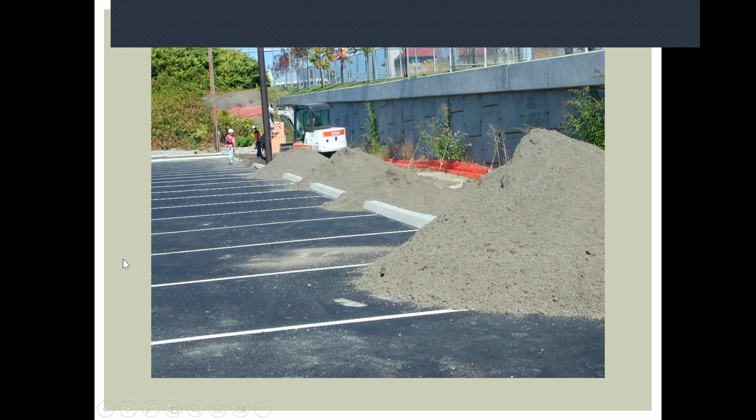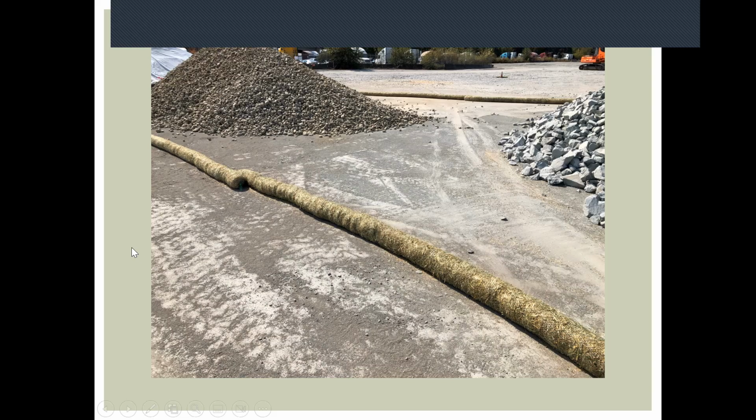Landscaper, you're going to have landscaping done. It's going to be raining in a couple of days. They want to bring in their special soil. Work with them to figure out the best place to put the soil rather than on the asphalt that would drain into a live storm system. Temporary stockpiles.